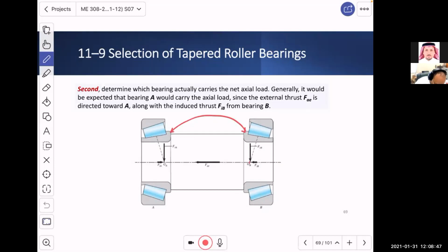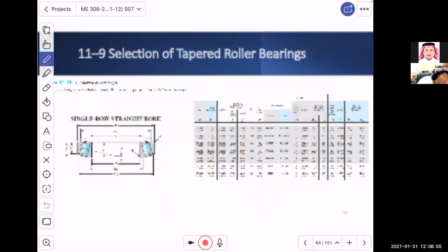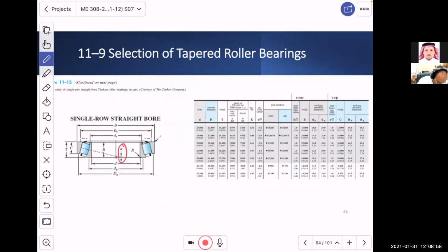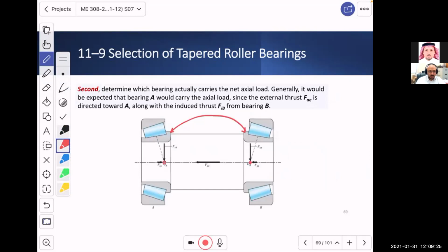Now, this point over here, which, by the way, if you go back to the drawing, I don't know if I put it here, over there, this is it, A. You see that little A over here as a dimension? This is how much from this side, which is the outer line of the bearing, you go inside a little bit. That little bit is how much deeper your effective point is going to be. And that effective point is here and there.